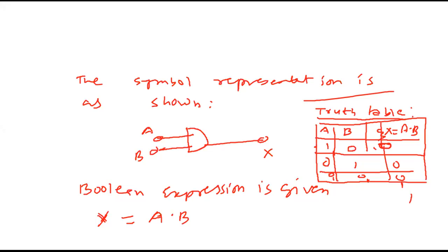This is the AND gate, behaving like two switches in series. It will give output only when both are working. That means only if both inputs are high is the output high. So the truth table is 0 0 0, 0 1 0, 1 0 0, 1 1 1.